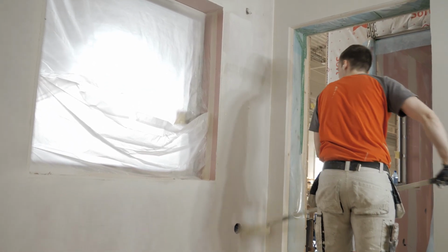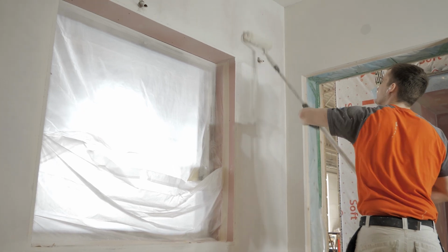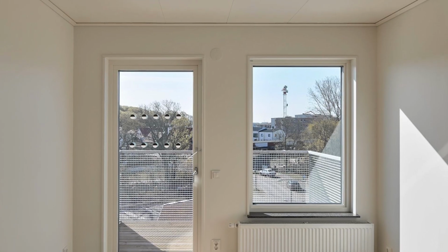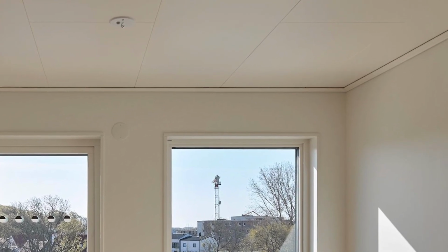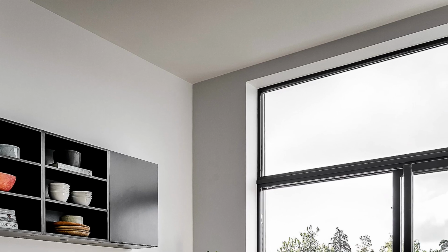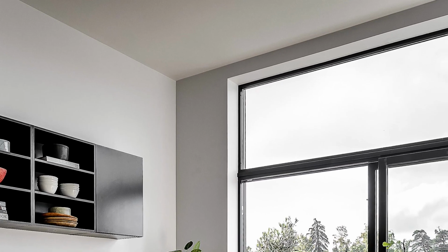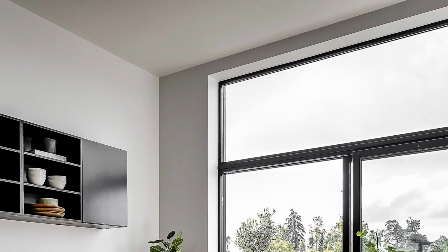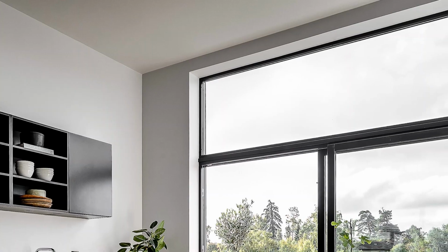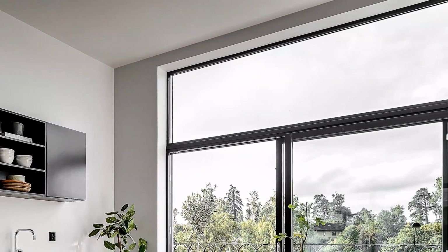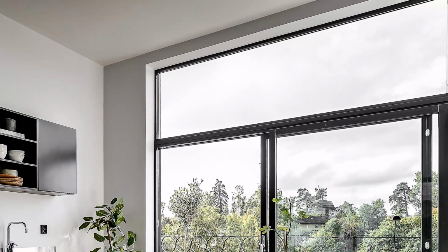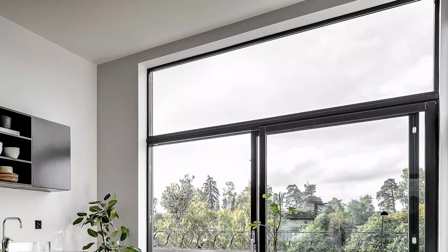Once wall and ceiling surfaces are finished, the corners need to be sealed. In the simplest case, corner moldings are used for this, which are fixed with slat nails. Another solution is to use corner reinforcements, which must be finished with elastic mastic to prevent the formation of cracks. Such a solution is more time-consuming, but the final result provides more refined finishing.